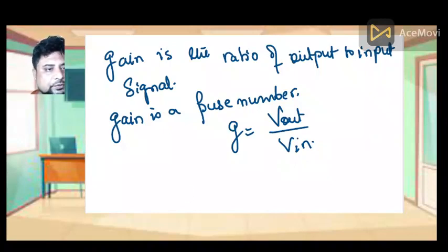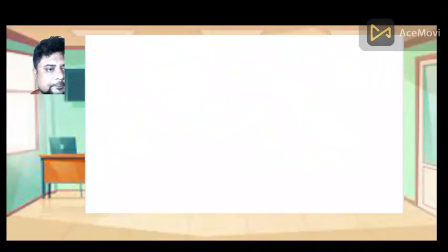Now, which devices can you use for amplifiers? How are amplifiers made? Let us come to that point. These amplifiers are primarily made of transistors. Transistors act as amplifiers. Transistors provide the power gain that is needed for electronic applications. Transistors can cause voltage gain, and they can cause current gain also. We will discuss the parameters related to current and voltage gain of transistors.